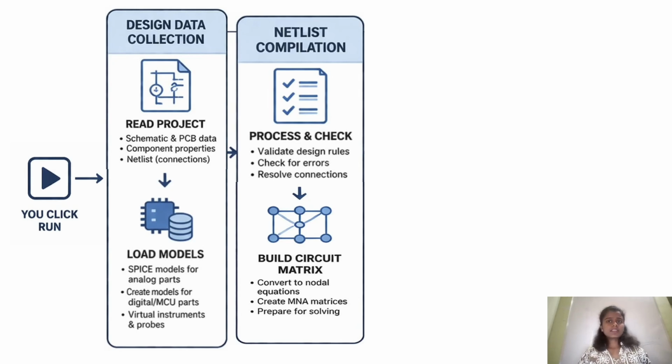Are all components connected to a power or ground? Are there short circuits? Is anything missing? If there is a problem, Proteus will either warn you or the simulation may fail. This is why proper wiring is crucial.